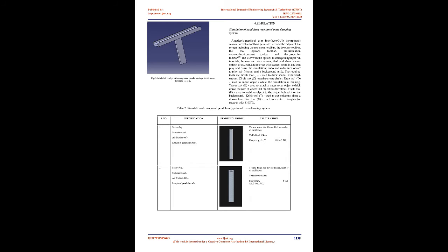The equivalent stiffness is WD/2L, and it follows that the effective length is equal to 2L. Each additional link increases the effective length by L. The tower, located in Osaka, Japan, is 157 m high and 28 m by 67 m in plan, weighs 44,000 metric tons, and has a fundamental period of approximately 4 s in the north-south direction and 3 s in the east-west direction.